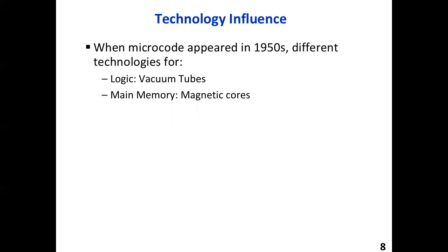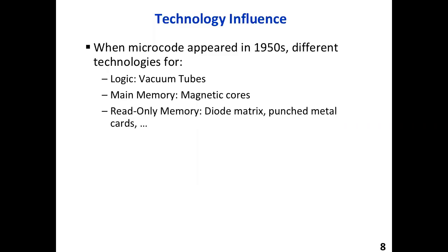It's a Monroe calculator. And then people decided they could store things using either vacuum tubes or magnetic cores or transistors. And the magnetic cores require that you magnetize a piece of iron and then read the collapsing magnetic field when you go to read the magnetic core. And people would thread these up by hand, believe it or not. Very fine work done under a microscope, and you could make magnetic core memory.